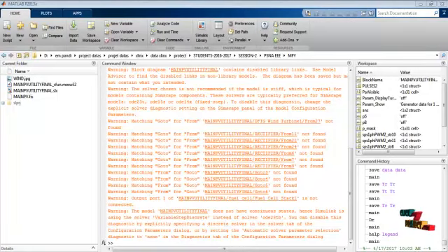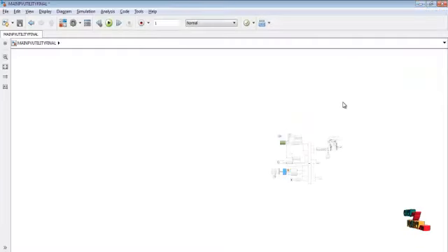Next we see the running process of our product. This proposed implementation is done in the MATLAB Simulink environment. First open the MATLAB window and create a new model file. After creating that, we arrange the elements from the Simulink library browser as per the circuit diagram. After arranging the elements as per the circuit diagram, we assign the parameter values for inductors, capacitors, panel and solar cell values.